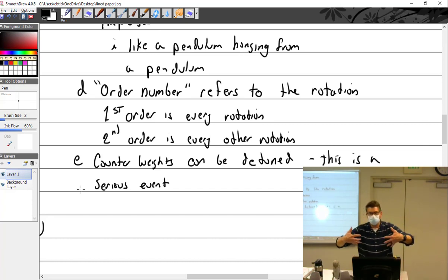Wow. And the cowling itself. And it wasn't like that 10 minutes ago. So it's not that they broke from the prop strike. It broke from the vibration of the detuned counterweights.